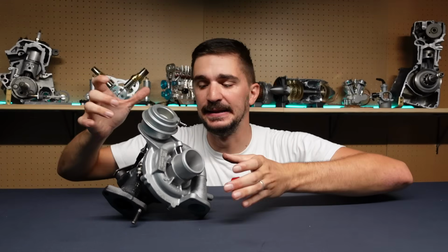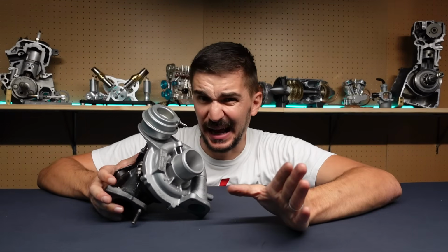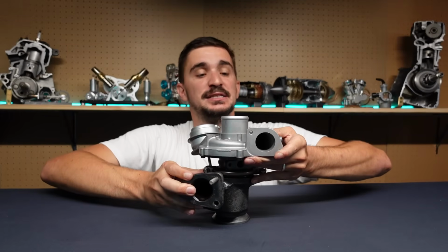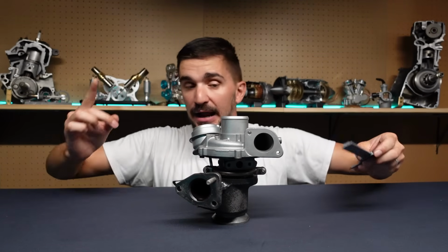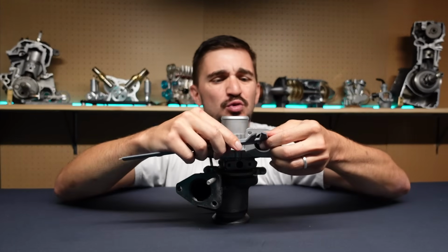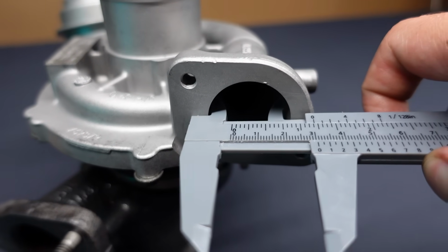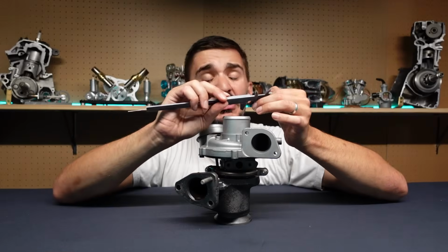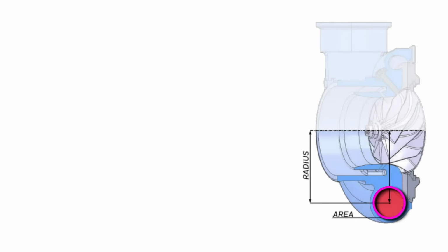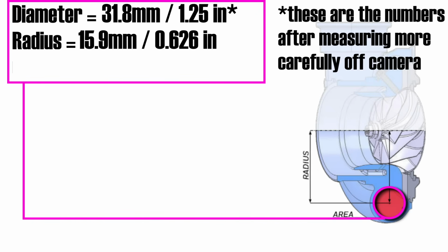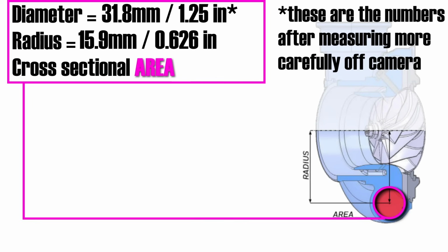How are they obtained? Well, you can actually calculate them, not very accurately, but we can try. Area over ratio stands for the cross-sectional area, which you can really only measure right here. If we're doing the compressor, at the inlet of the compressor, we have around 30-ish millimeters. Because this is Garrett, it's going to be inches, so the radius is 15 millimeters, which is this much inches, and cross-sectional area is pi radius squared, which gives us this number.